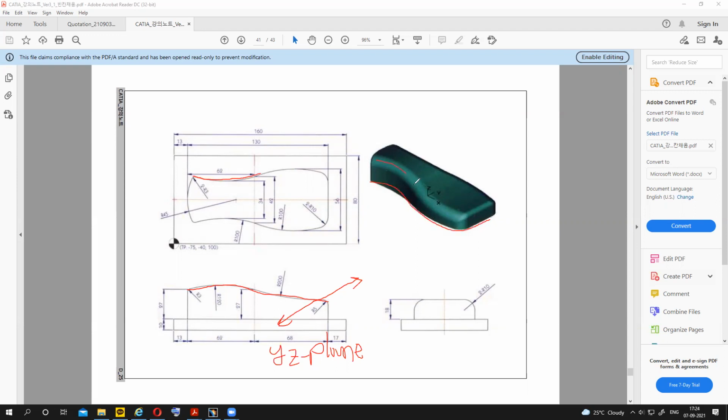So I finish this one, right? Extrude. And later we make the top view like this one, and extrude in this direction, and where both sketches are meeting we have to cut that one, because we don't know the exact details of this dimension. So we have to trim that one. Let's do this one first.